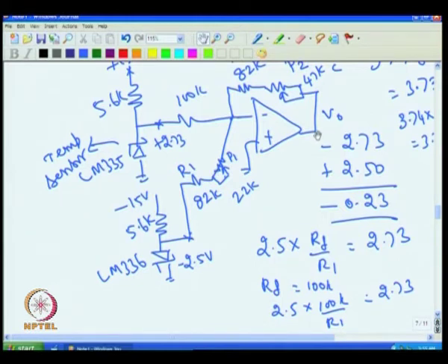That will give here at this point 10 millivolt for 1 degree, because 0 degree is 0 volt, 1 volt is 100 degree C, that means every degree 10 millivolt change occurs. Now, if you change 7.5 millivolt here, the output also will change by 7.5 millivolt due to the temperature variation of this. So, the output will have an error of 0.75 degree, because 7.5 millivolt corresponds to 0.75 degree error.